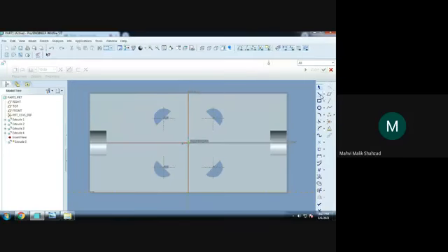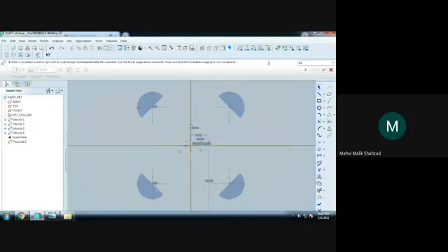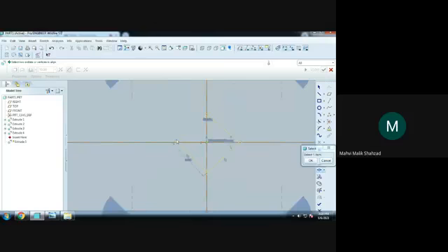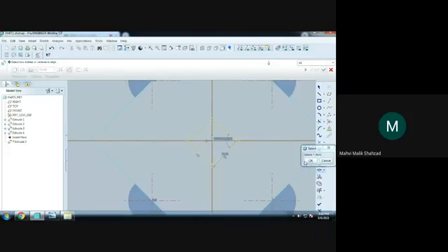Okay, here again randomly I will make a square. Then what I will do, I'll go for geometrical constraint, coincident this with this, again this point with this point. Then this dimension is given to us, that is 12 mm.